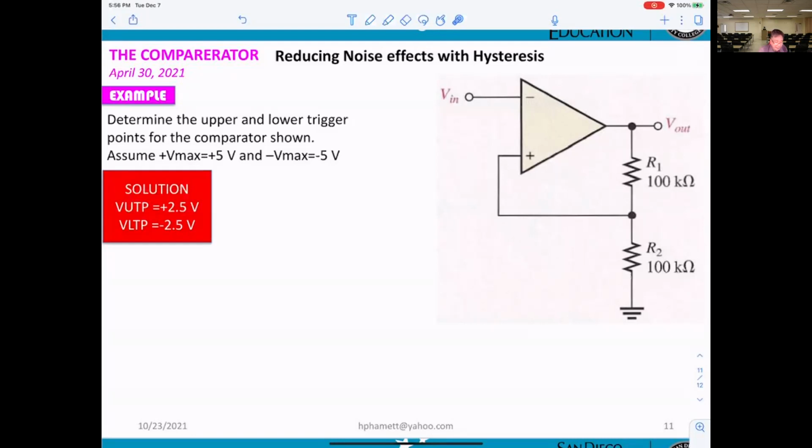First thing, yeah. So basically you put that information that you just gave us back into the formulas that you just gave us above? Yeah, the thing is when they want to hit the region, what's the first thing you have to do? Calculate the V upper trigger and V lower trigger. Right. So now, if I'm doing a calculation and I get the upper trigger is plus 2.5 volt, do you understand how I get that voltage?